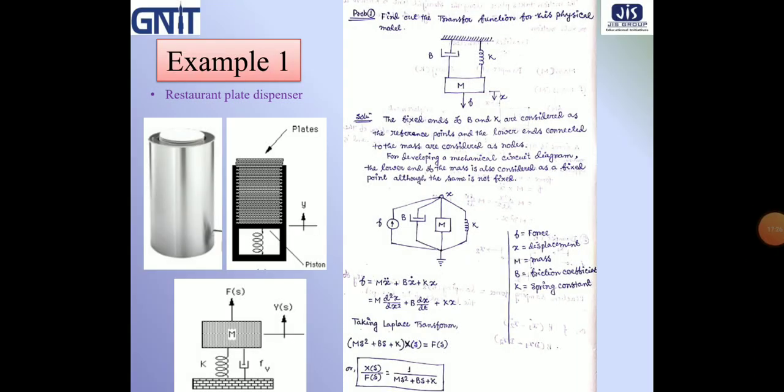This is the way we have to calculate the transfer function. Whichever type of problem is given, you first draw the mechanical circuit diagram, then write down the force equation, then perform the Laplace transform of this force equation and arrange the equation as output by input in the Laplace domain.